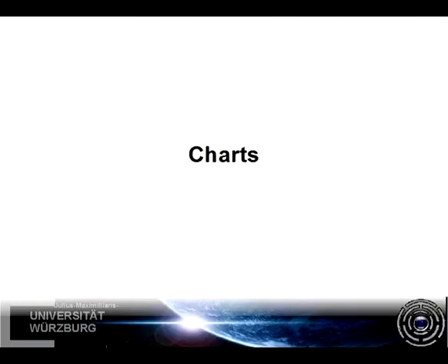Finally, let's take a look at how aviation charts look like and how they are used. There are two kinds of flying. The first kind is called VFR, Visual Flight Rules. VFR means that you navigate primarily by looking outside, using visually identifiable references like rivers, bridges and highways. Nevertheless, the VFR charts contain, amongst information about such visual fixes, also information about radio navigation aids like NDBs and VORs that the pilot can use as additional reference.